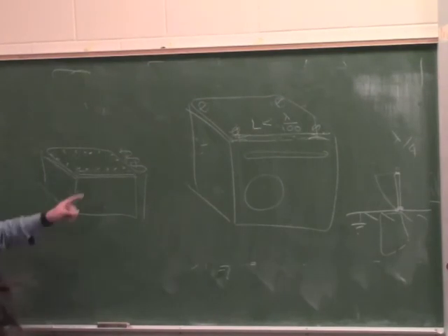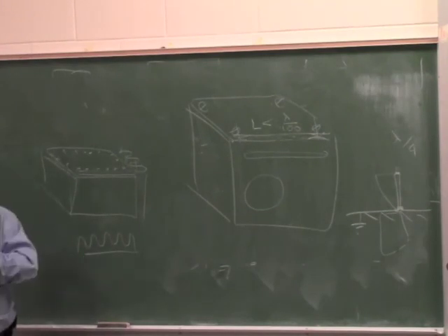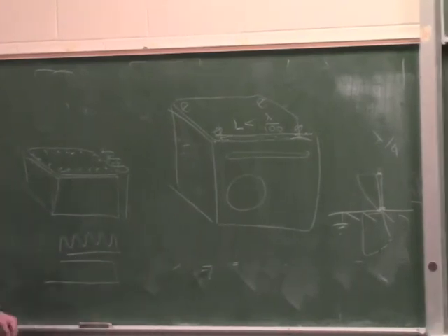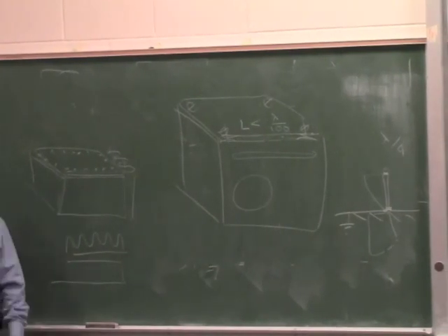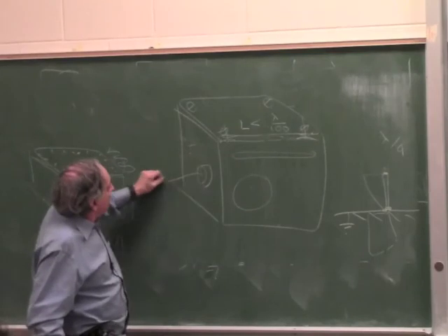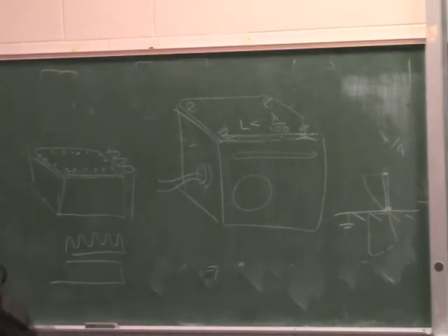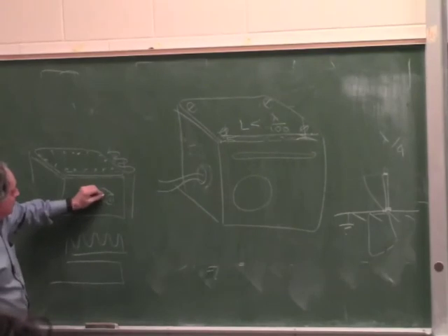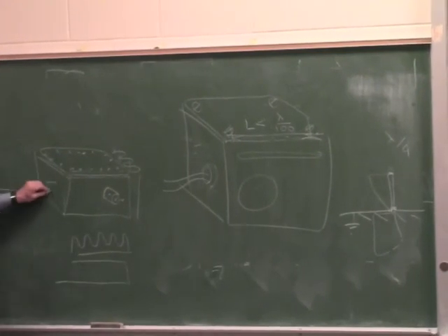If you ever open some RF stuff, you see this gasket. Sometimes it looks like this. It's flexible metal fingers which are compressed, and sometimes it looks like conductive rubber, silver colored rubber, which is actually silver filled silicone rubber, so it makes continuous electrical contact. Now the same is true when you connect the shields. When you have an audio box, you have some plastic connector and a wire comes in, but the plastic around it is not grounded. If you have an RF box, you either have some BNC connector, which is shielded all around, it's metal, or if the wire comes in, you'll see the wire will come in with a braid, but the braid will be soldered to the box or to a fitting. So it's all metal, it's all covered with metal.